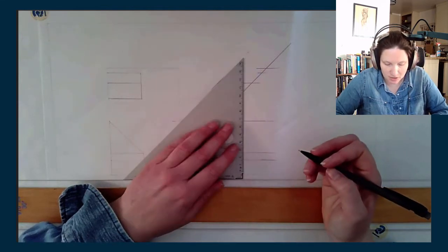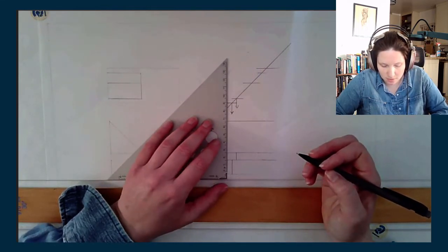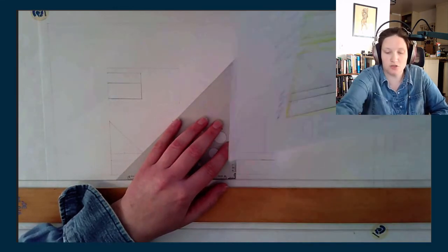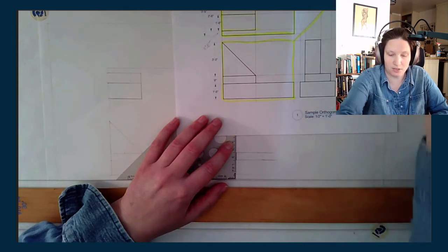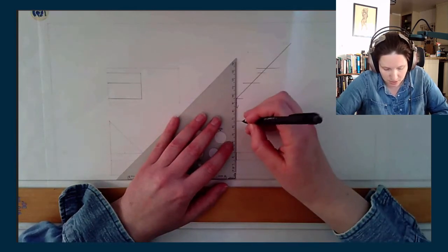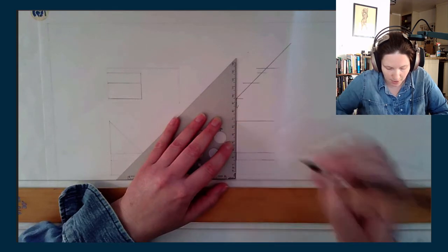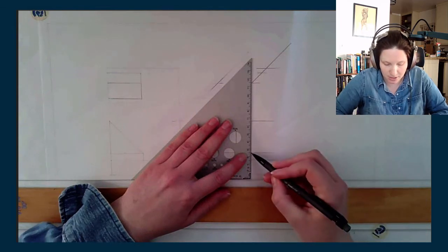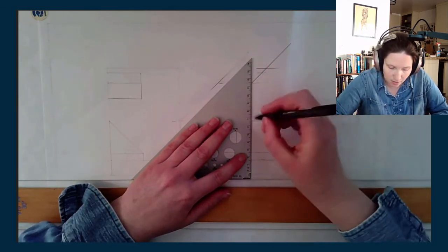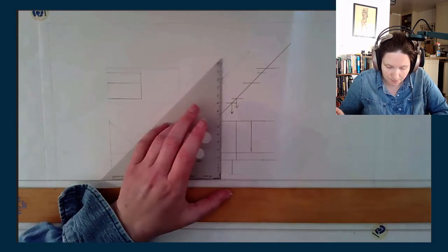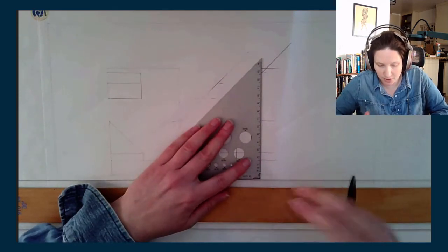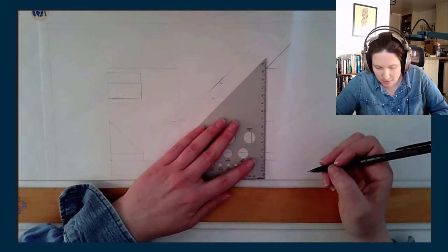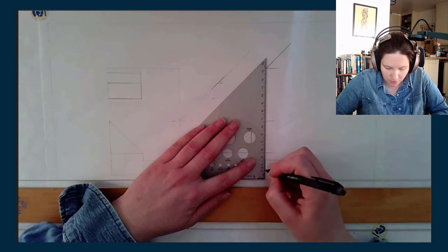Okay. And then the next one, oh, and it's actually going all the way up, right? Because it has the 2 by 4 sitting on top of it right here. So we'll go all the way up to that top edge with this step. Okay, yeah? The next one is the other edge of the 2 by 4, so it'll stop here above the 1 by, right? And then I'll transfer the other side of the 1 by and the other edge of the base 2 by 4.